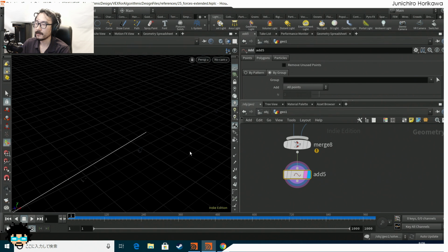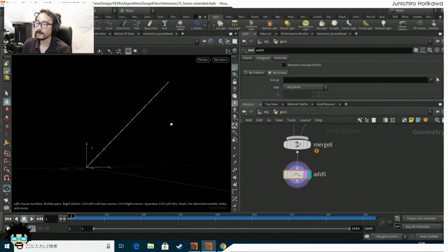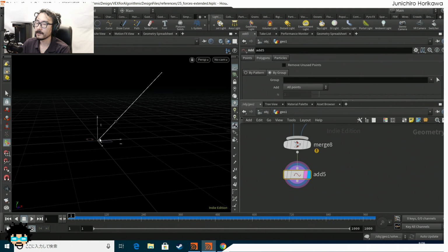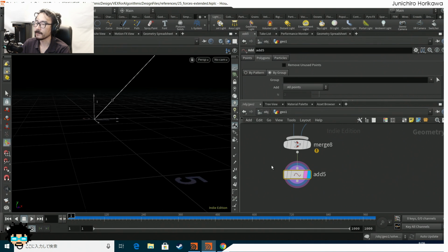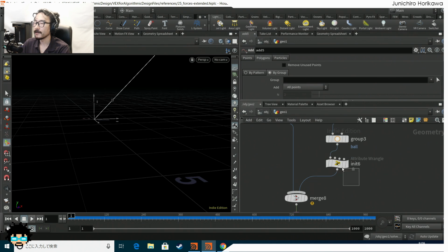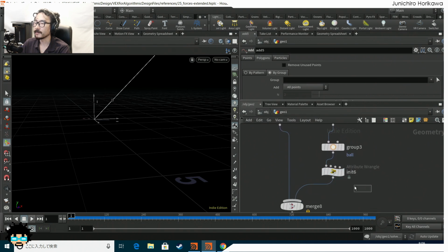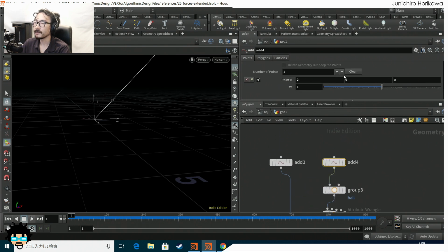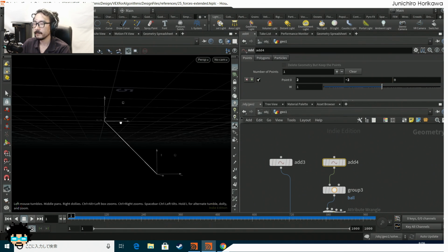Now the new line has been created. Now I want the second point to be underneath, in the y direction, because I'm also going to apply some gravitational value, the gravity value. So let's make the initial position to be -2 for the y. That's good.